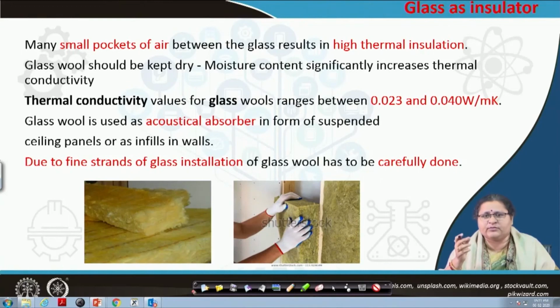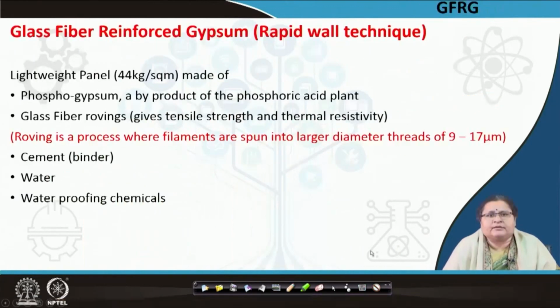Otherwise, it is an excellent material for being used as a thermal as well as an acoustical insulator or a sound insulator. Now let us see, apart from the application of it in bat or roll form in thermal or acoustical insulation, we can actually use these glass fibers as a reinforcing material in gypsum.